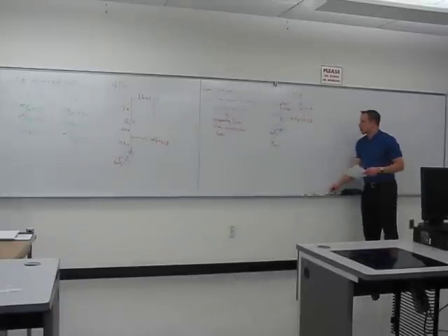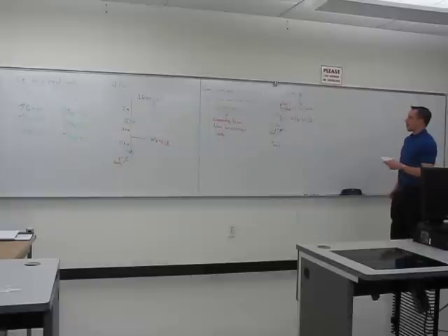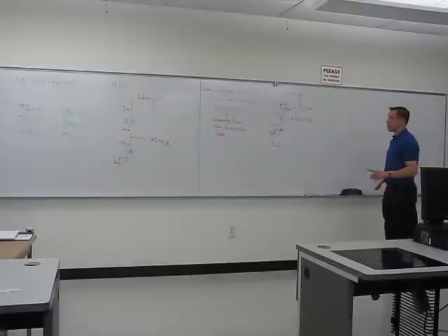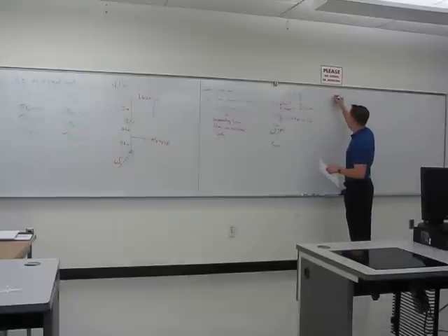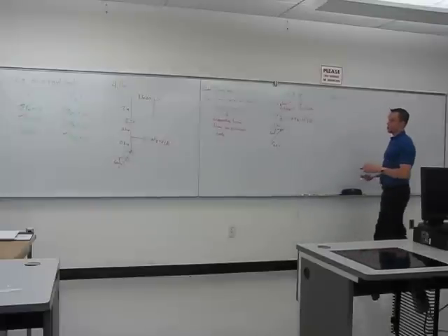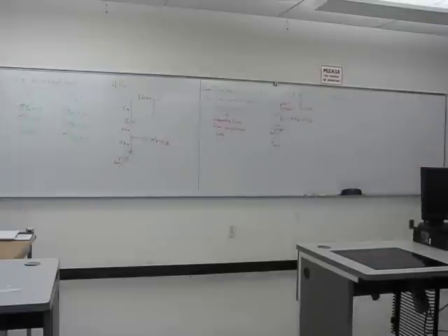All right, so let's see. We have a rigid body in equilibrium. So that means the sum of the forces in the x direction has to be equal to 0. The sum of the forces in the y direction has to be equal to 0. And the sum of the moments around the z-axis, the sum of the moments around any point, will have a z component equal to 0. So let's start with the x equation and see what we can figure out from that.